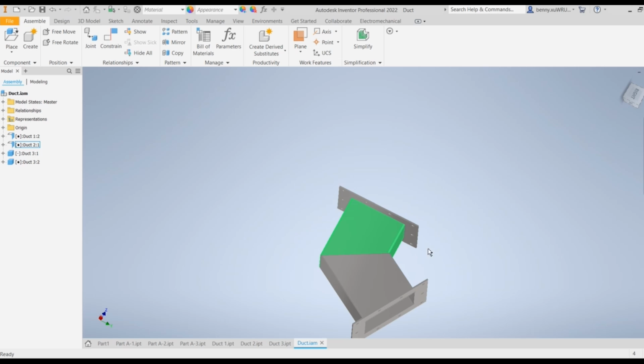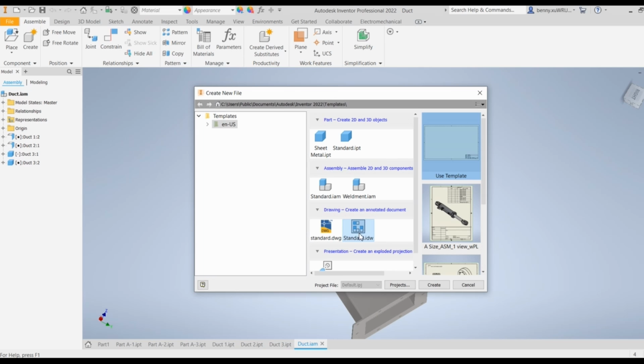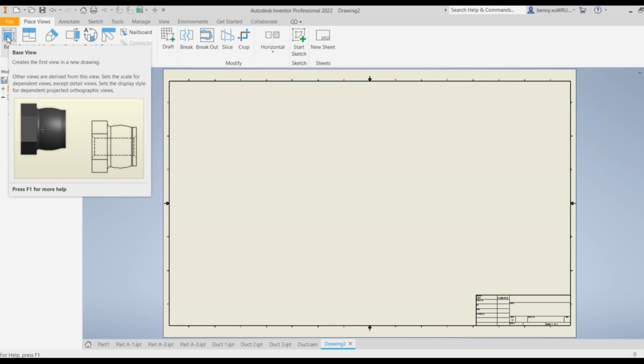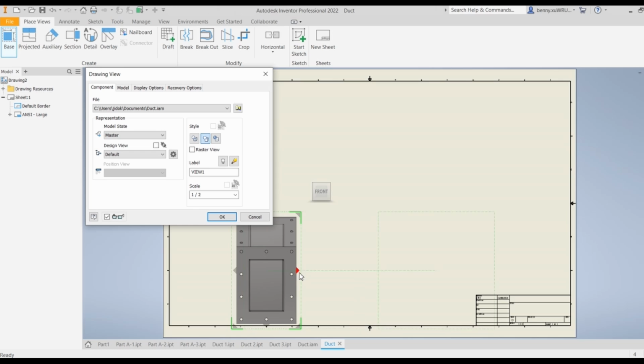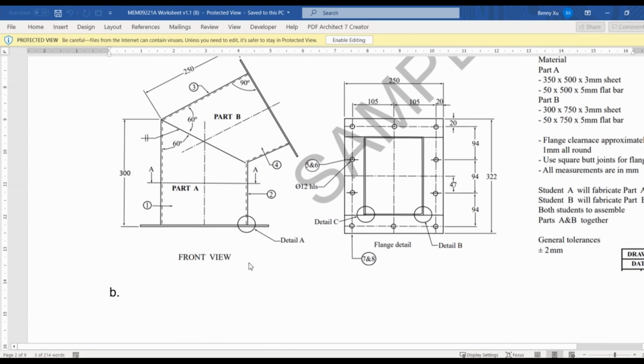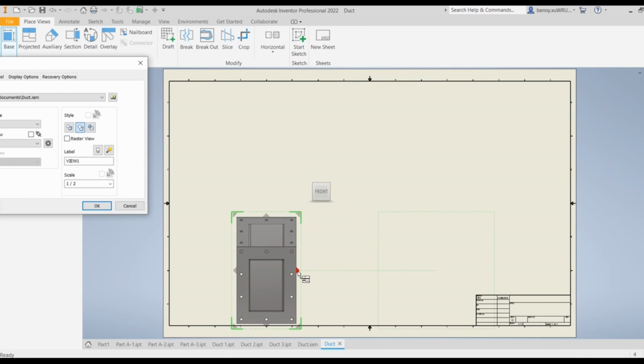And say OK. Okay, after save, go to new IDW. Here, create base. Remember, whatever we save previously, they will place to here straight away. See that? I'm going back to here. I want to see that's the front view.